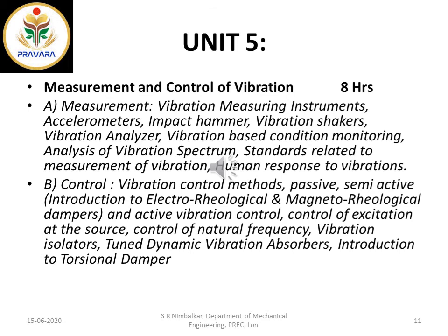In condition monitoring, that is vibration condition monitoring, it is based on measuring values of specific parameters which are critical to failure, isn't it? If the part is wearing out, meaning more wear has happened, then the tolerance, or the fit between the mating components, goes wrong. In dynamic conditions it makes big noise, or the vibrating parameters give erratic readings, isn't it?